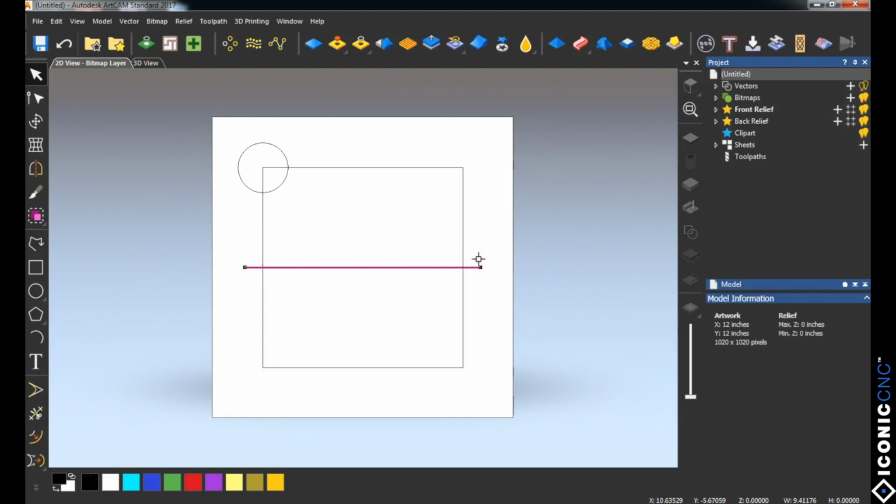And then lastly, I want to center this line in the middle of my workspace. So I use the F9 key on my keyboard. F9 is a shortcut key for center and model, and I've pushed F9, and that's now centered my object in the middle of my workspace.